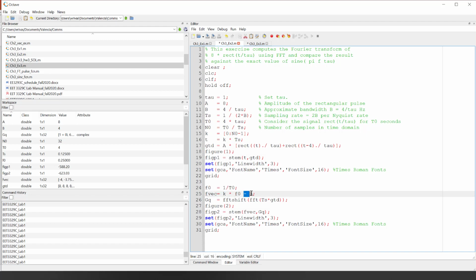Now, let me explain this b in just 1 second. I'm going to come back to it. When I calculate the FFT, right, there's the calculation of the FFT. The FFT doesn't create the frequency spectrums in the way we're used to looking at them. So we always look at them with frequency of 0 in the middle, and then we see the negative frequencies and the positive frequencies. Well, the FFT doesn't do that. Doesn't like it or it's just the way that it got developed. The FFT keeps everything in the positive frequency domain.